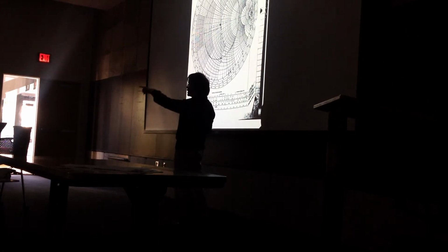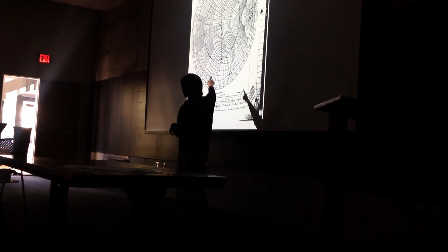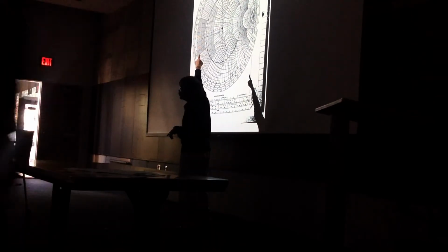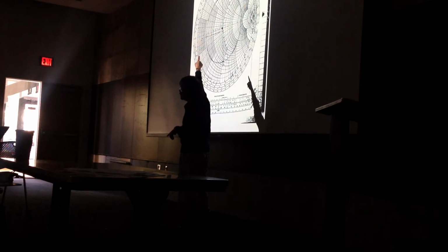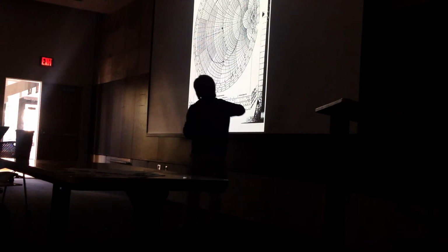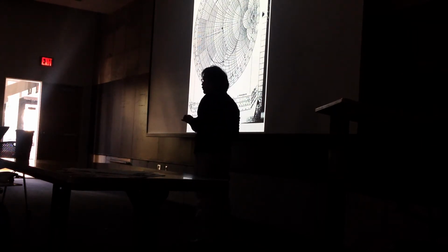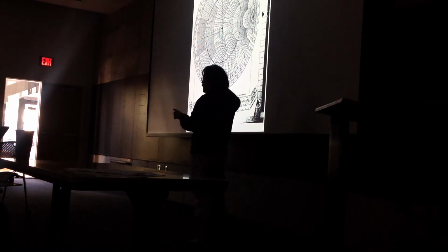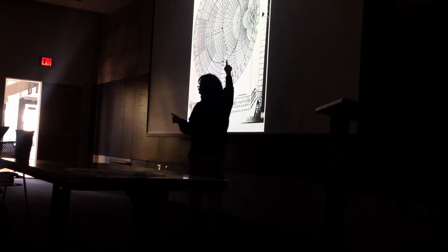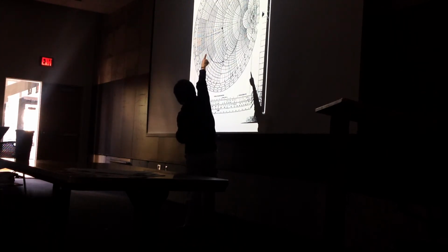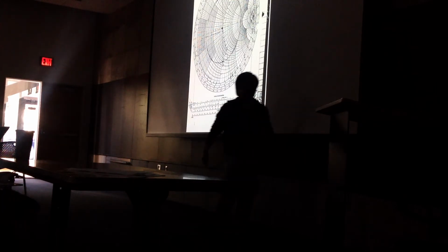And the second step, I take that impedance and rotate 180 degrees to the other side. That will be my normalized admittance. Now, where do I want to go in order to do my matching? I take that constant circle and intersect it with the R equal to 1 circle. That's where I get that point, which I label as Y at that location.